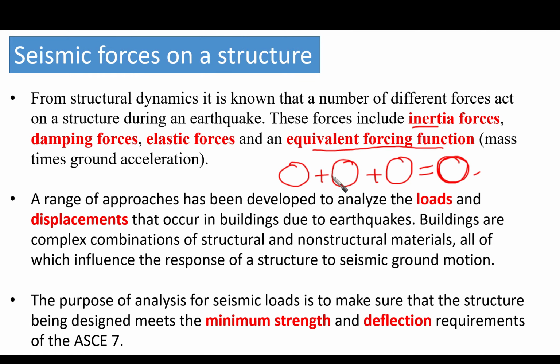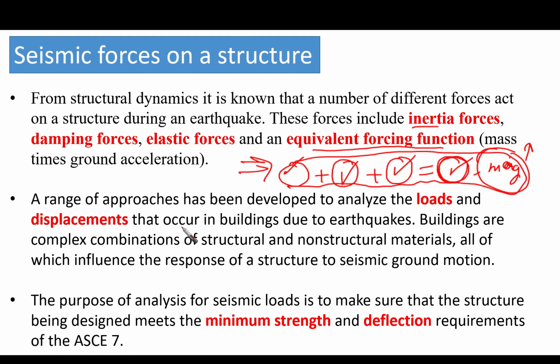So actually this is the inertia force here, this is the damping force here, the elastic force, and here this is the equivalent forcing function, mass times the ground acceleration, m times the acceleration of the ground. And you can go back to our previous videos to understand the rationale behind this equation of motion.